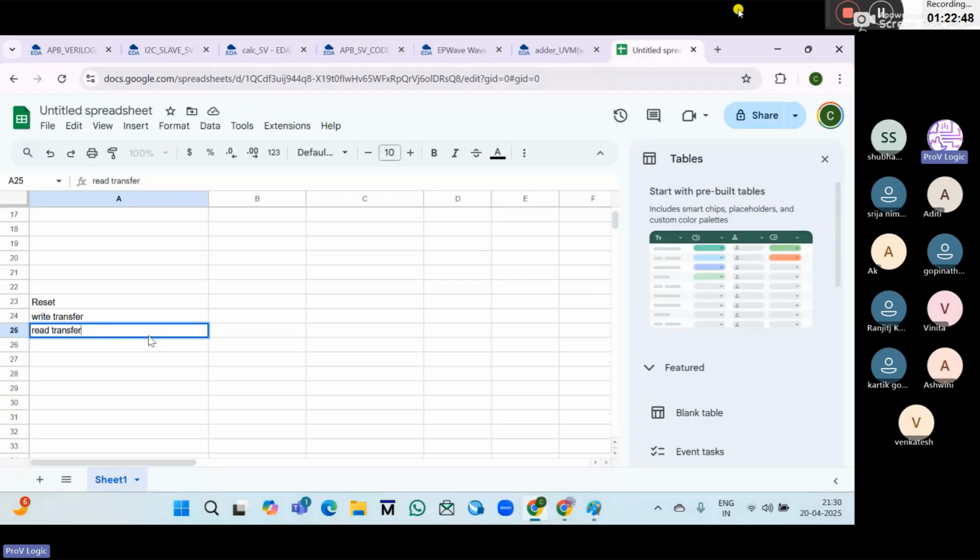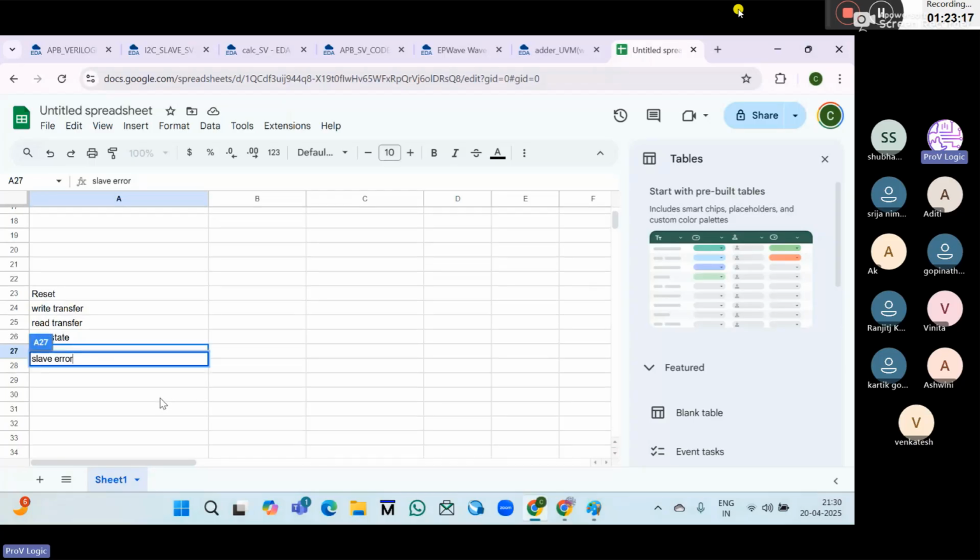And next you need to check whether there is a wait state or not, so PREADY is asserted or de-asserted. You want to check the wait state, so that is one test. Nothing but checking all the features. Any other features? Slave error, you can check that, that is one feature. So like this, write all the features and whatever possible scenarios you want to verify.